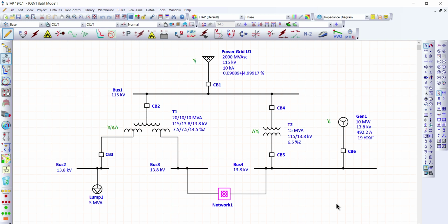These are three-phase ungrounded fault, three-phase grounded fault, phase-to-phase ungrounded fault, phase-to-phase grounded fault, and phase-to-ground fault. Line-to-ground fault in utility systems can range from a few percent to perhaps 115% of three-phase fault current. This will occur only if the zero sequence reactance is less than the positive sequence reactance.